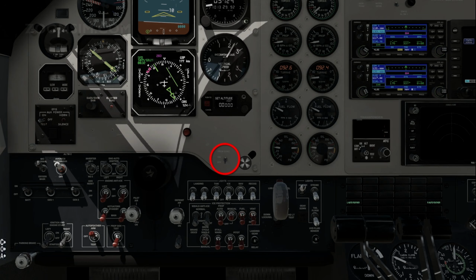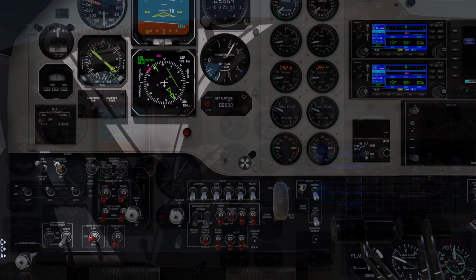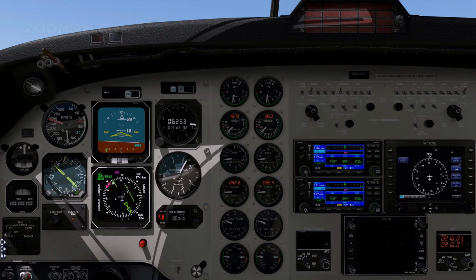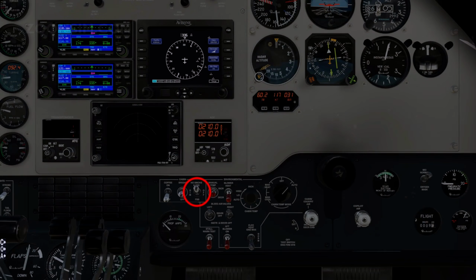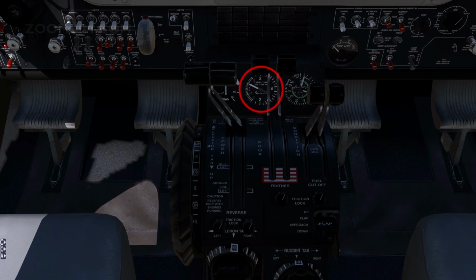Synchro phaser on. The synchro phaser is an electronic system which matches the RPM of both propellers, establishing a blade relationship between them and reducing cabin noise to a minimum. Auto feather off. Engine instruments monitor. Cabin sign as required. Cabin pressurization check.